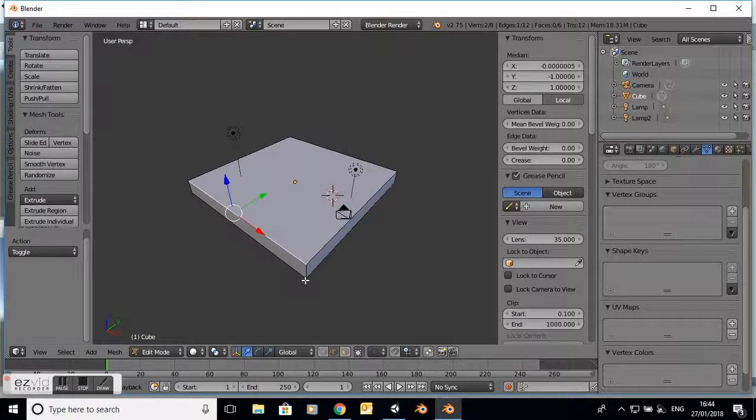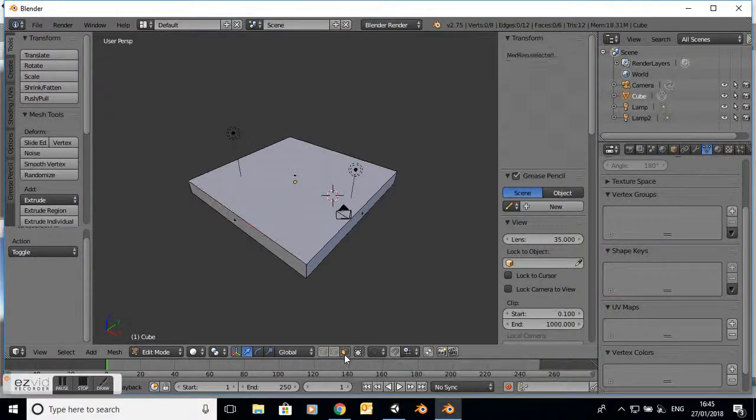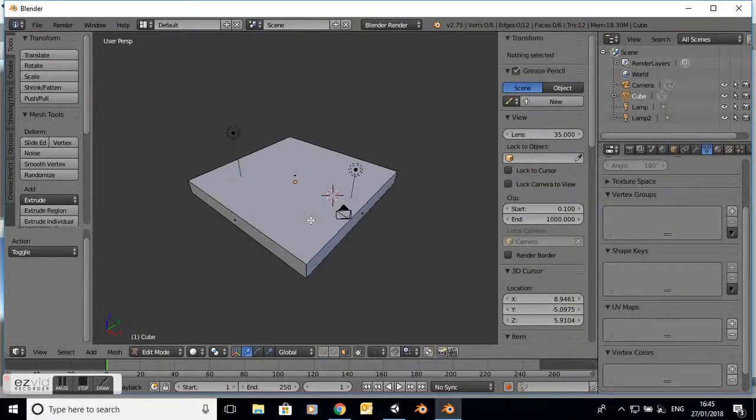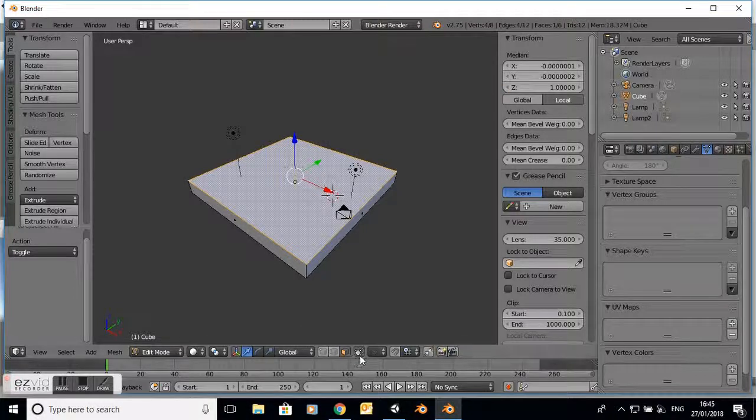But in this case, I want to select this surface. So the other one here is for face selection. Choose that, and there it's that. There's another button here which is an important one to know about. With this one you can select vertices, edges or faces on the other side at the same time if this is on. We don't want it on at the moment, it's off. So I have now selected this top surface.